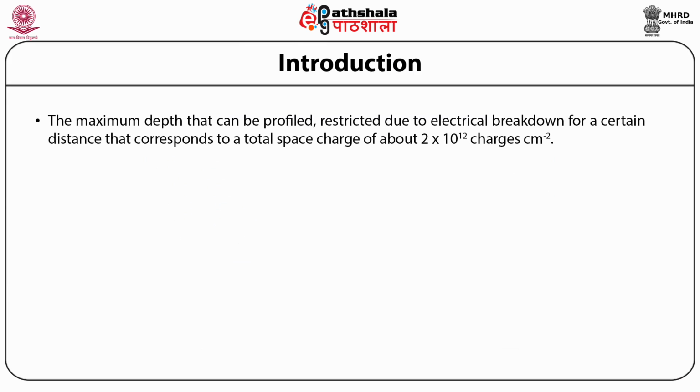The maximum depth that can be profiled is restricted due to electrical breakdown for a certain distance that corresponds to a total space charge of about 2 × 10^12 charge per centimeter square. Furthermore, CV profiling of low bandgap materials and materials like InP is difficult.